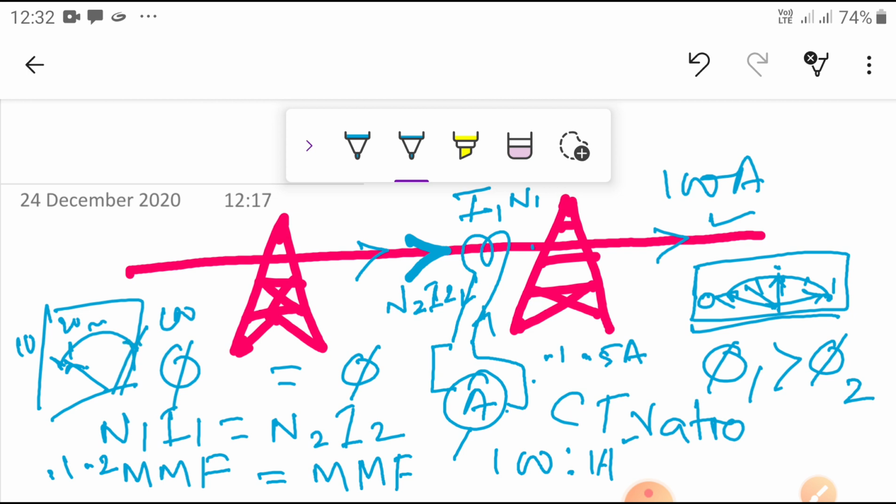So whatever the reading shown by this pointer on the calibrated scale is the current which is flowing on the primary side only. But actually, what is the current flowing in this one? 0.1, 0.2, 0.3 amperes only, less current. That's such a way that high current is measured by using this meter calibrated such a way that sometimes, if I don't want the values placed in the 10, 20, 30, 100, I can use the same 0.1, 0.2, 0.3, whatever the current is coming here.